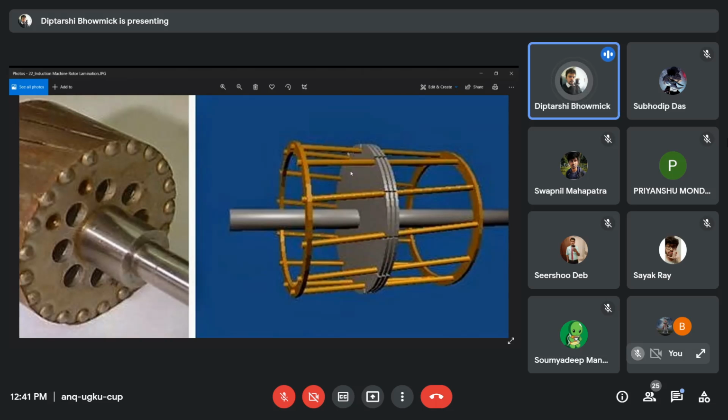And it is a three-phase, alternating magnetic field. So when the EMF is positive over here, let us consider that the direction of current is from right to left. When the current is from right to left in this bar, then in the bar diametrically opposite, the direction of current is from left to right, because this is AC.